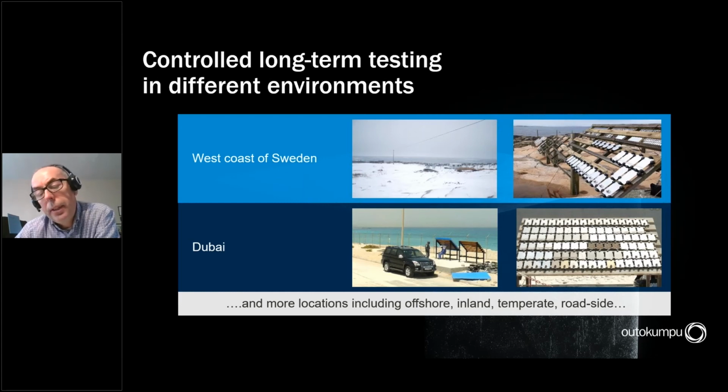And on these test sites, we study not only the steel, but we can also study bolted connections through crevice joints. I think on some of the samples, you can see some bolts attached. Some of the samples we can put weld beads on as well and study the performance of welds. So this is quite a good way to get very good data and information about long-term performance.